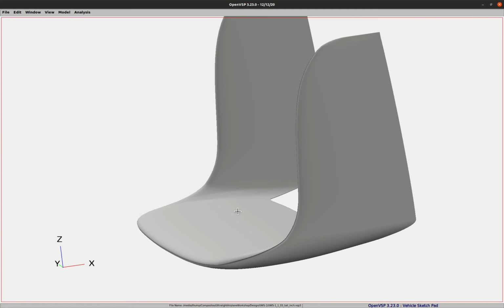And just as a point of information, I did not select this twin vertical tail arrangement just to try to reduce the interference drag. I selected this because I'm going to have twin propellers in front, and I wanted to have these vertical tails in the propeller slipstreams so I can have better directional control authority if one of those motors should happen to fail. So I'm actually going to have increased drag because these vertical tails and a portion of the horizontal tail are going to be in that propeller slipstream.